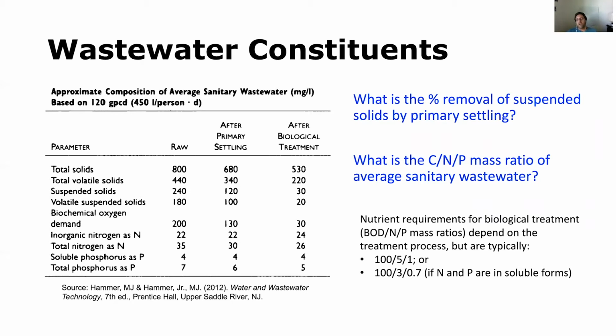And if we're talking about situations of reuse, like for non-potable reuse, in some cases we may not need to remove the nutrients because maybe the nutrients can be beneficial for irrigation purposes, for example. However, if the intended reuse is indirectly connected with potable water use, then we would need to achieve very high levels of pathogen reduction, very high levels of organic matter and solids reduction.